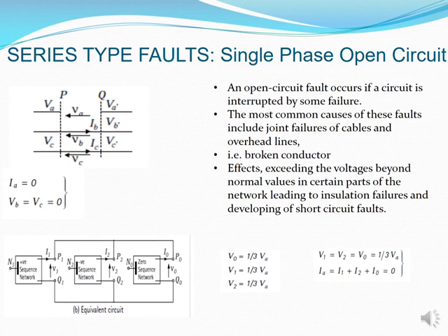So you are going to have a voltage that is going to show as your fault between those two places where the open conductor is. So at the bottom, we're showing then what our phase sequence voltages are going to be, where V naught is equal to V1 equal to V2 are all equal to a third of VA.